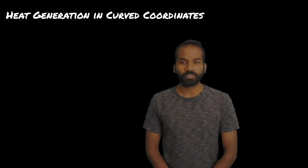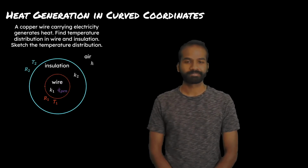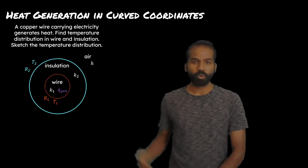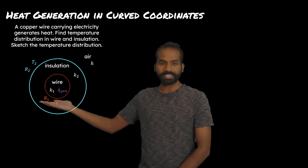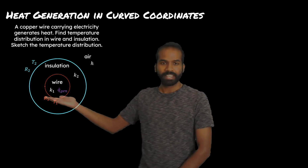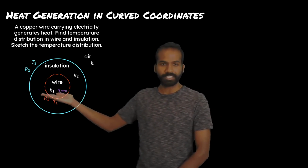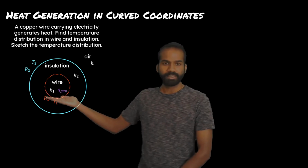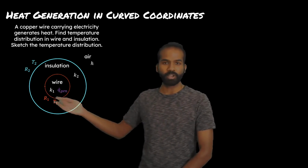We can extend what we learned about heat generation in Cartesian coordinates to curved coordinates. Let's look at a copper wire, which is carrying electricity, and because it's carrying electricity, it's generating heat. This wire has dimensions of r sub 1, that's its outer radius. It is generating heat at a rate q dot gen, and has a thermal conductivity of k sub 1. The outer surface of the wire is at a temperature of T sub 1.